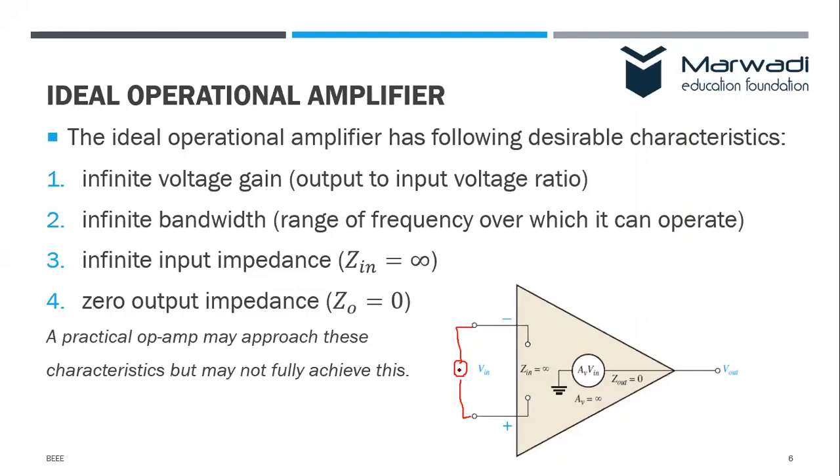Now you know that the signal which is coming from the sensor may be very, very weak, right? So let us take an example of a brain wave or the heartbeat. If you try to detect the heartbeat, that signal is very weak, right? Now, if you want to operate on this signal, then you must amplify it. Okay.